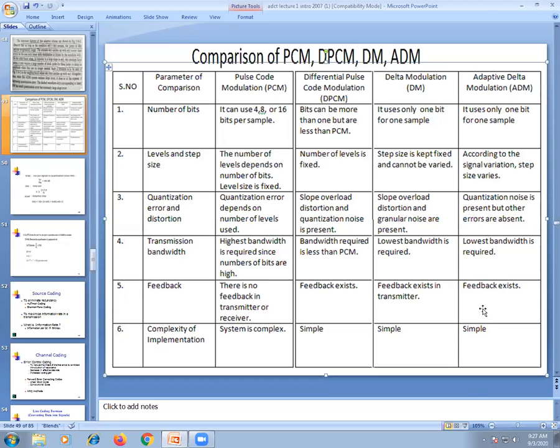The processor quantizes the level of the steps for increasing or decreasing, because the step size is not uniform in adaptive delta modulation. The step size is uniform in delta modulation. Students, note that this is an important point in the difference between delta modulation and adaptive delta modulation. In delta modulation the step size is uniform; in adaptive delta modulation the step size is not uniform. That's why you require a digital processor.